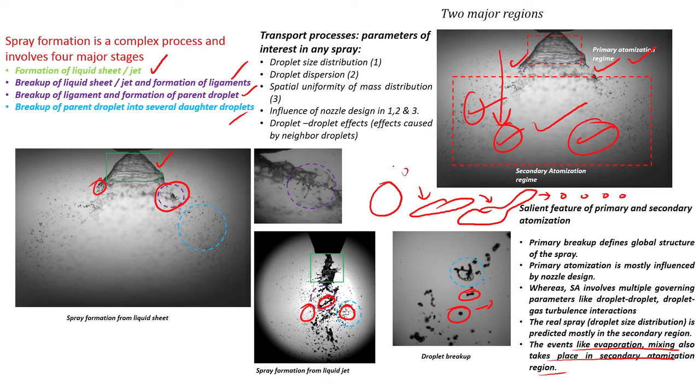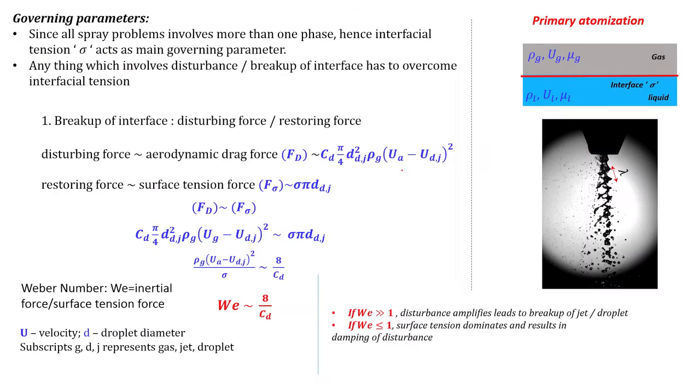As it becomes very small, surface tension becomes very important, and those droplets become very stable, okay. So, when evaporation and mixing take place, the droplets can be considered spherical. So, all the analysis that we did earlier on droplet evaporation holds, but not for very large droplets, because large droplets are unstable inherently, especially in a high speed flow. It depends on the flow conditions. It is not that they are unstable by nature, okay. It depends on the flow.